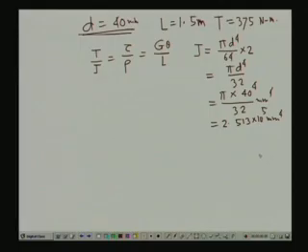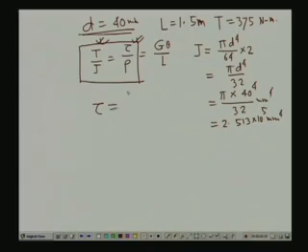Now, what we need to evaluate is the shearing stress tau for the given twisting moment. So, we take the first part of this equation, where we write tau as equal to T times rho divided by J. Now, the twisting moment T here is 375 Newton meter. So, 375 into 10 to the power 3 Newton millimeter, multiplied by rho. Now, rho, if you remember, is the radius.